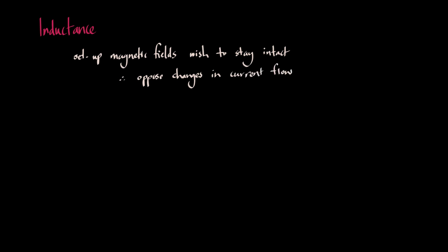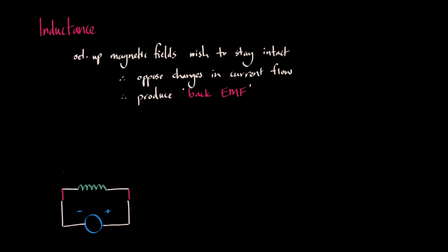This temporary resultant potential is termed the back electromotive force, or back EMF, and can cause a lot of issues if handled incorrectly. As a visual example, if we were to disconnect an inductor from a current source and immediately connect it to a resistor, the inductor would instantly create a voltage drop opposing the change in current. Therefore, current would flow through the resistor for some time.